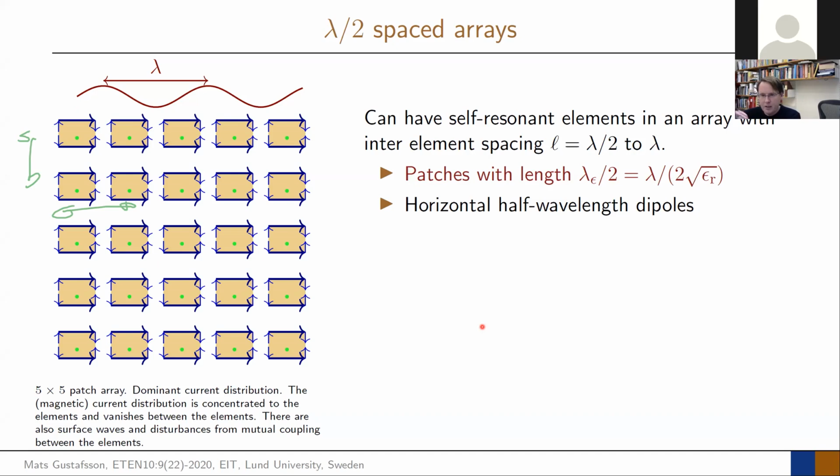And of course, this doesn't have to be exactly lambda over 2. It works with having lambda over 3 or 0.6 lambda, but in the order of lambda over 2. That's what you need. Yes, but the distance should be in the vertical or horizontal side. I think in the one I've been drawing, it's the same. And to make it really lambda over 2, it will be the same. So this would be what's called a linearly polarized array, and it's here lambda over 2. But you don't have to have the same in, let's say, this distance here, I can call this dx, and I can call this dy. They don't have to be the same. But if you say a lambda over 2 array, they are the same.